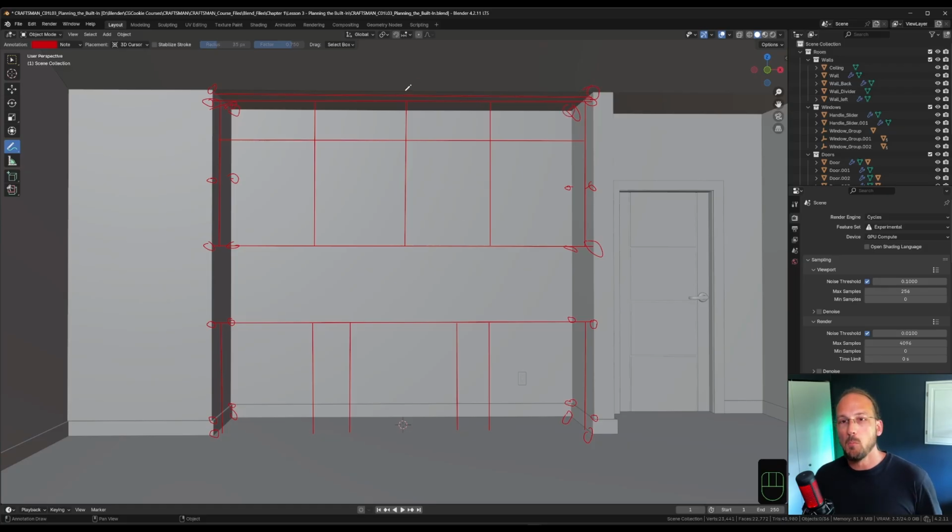It's always better to take more measurements rather than less. That way you can avoid problems from the get-go. And then we're also going to take the same thing in the middle, because usually ceilings cave a little. So those are the measurements that we need to take. And then, as I mentioned in the first site assessment already, we also want to check the height of the baseboards to see if we get any problems with those. And then we should also make sure where this is, to make sure we don't have the side of a cabinet right in that position. Although with the size of the cabinets that we're planning here, I can already see that is not going to be an issue.